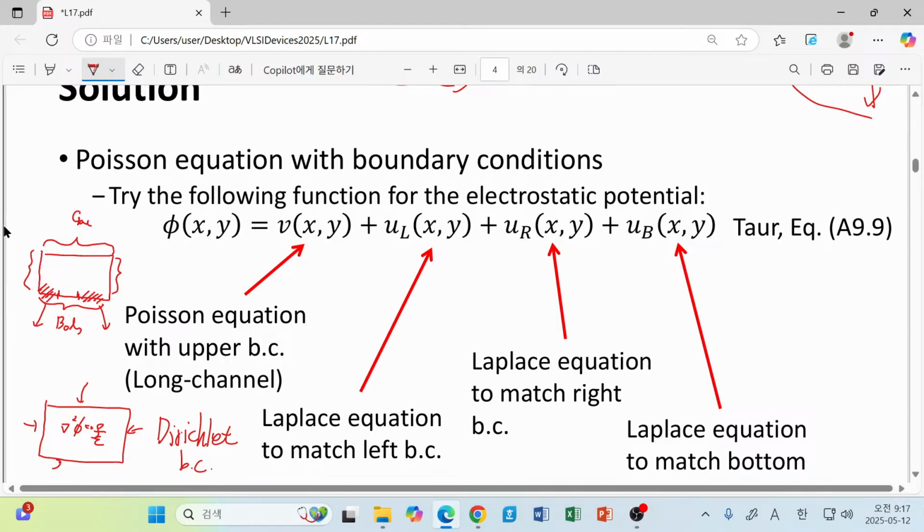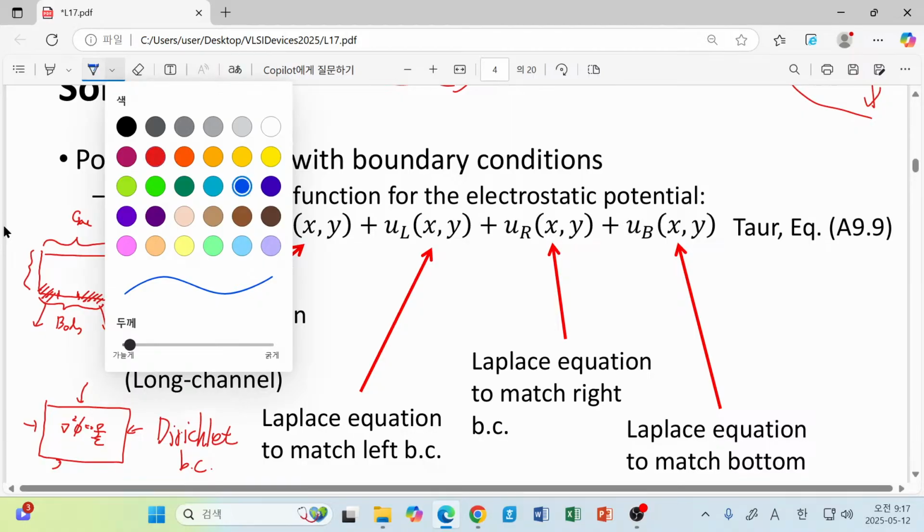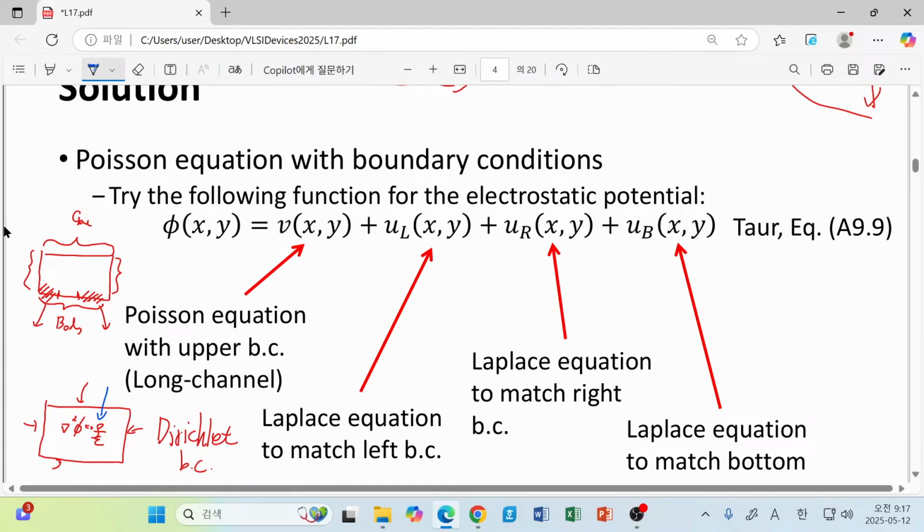An even better thing is, if rho, the net charge density, is a function of the potential once again, then we must solve a non-linear equation. But fortunately, since we have neglected the contribution from electrons and holes, this rho, the net charge density, is a given number. Inside this silicon system, that is just Na.